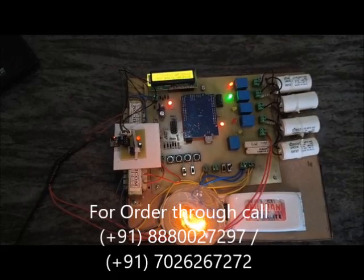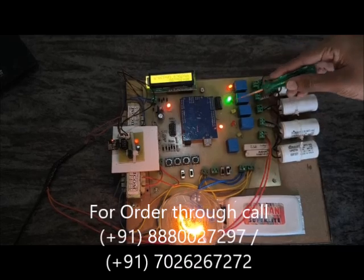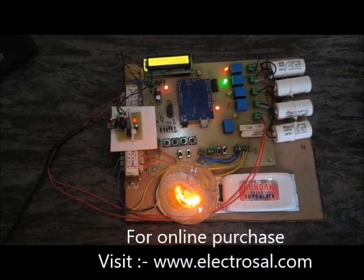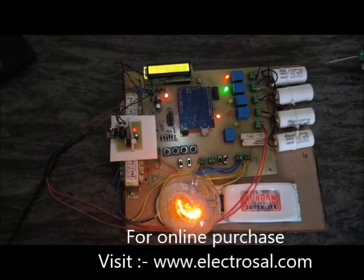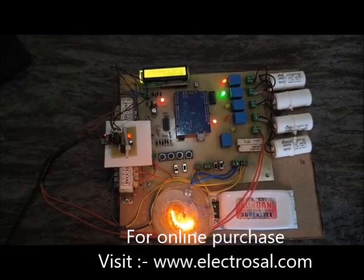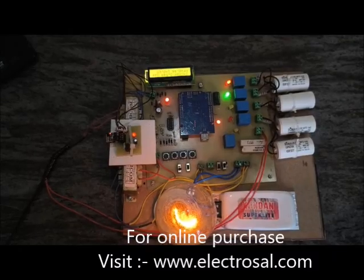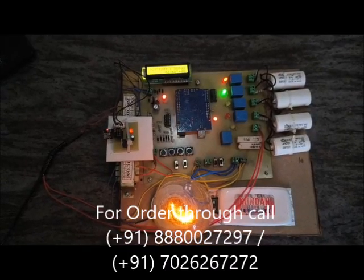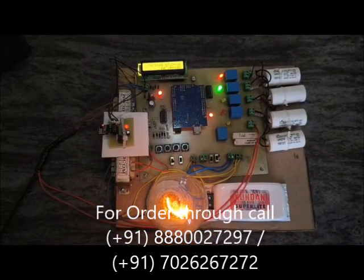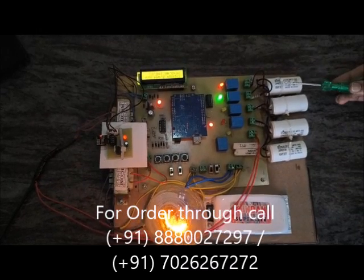Since the current lag is higher, the controller automatically switches on two capacitors for compensation. When the system enters the compensating mode, it tries to correct the power factor. However, due to continuous variation in power factor, the capacitors may switch on and off repeatedly. To avoid this fluctuation, we keep the system in lagging mode.